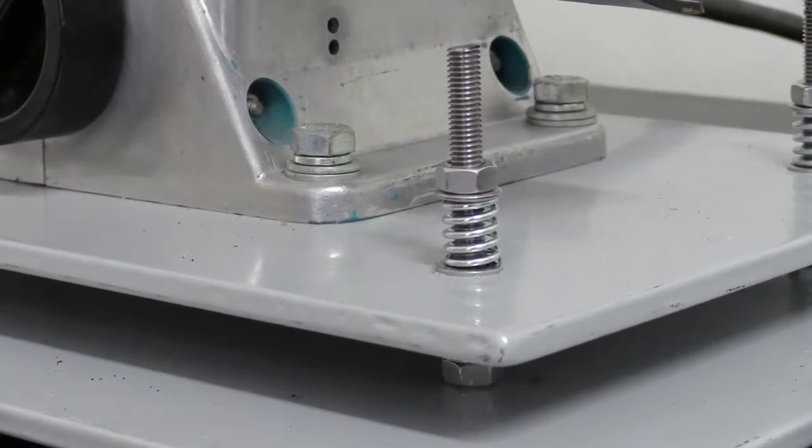Bump test is one mode of VA4Pro analyzer produced by Adash. It was developed for situations when you suspect a resonance problem. What is it, the resonance? For every mechanical object, the frequencies exist on which this object vibrates easily and higher than on other frequencies. We call them natural frequencies.